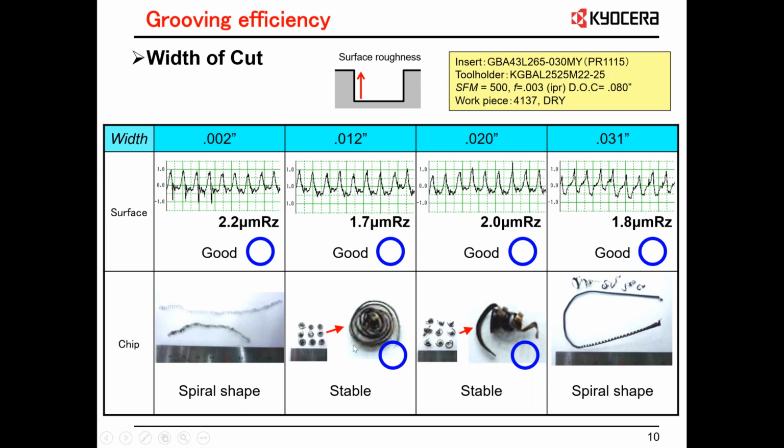Here we're completely engaged to the radius width, and it's running down the side of the chip breaker, where it actually has chip control from that MY because of the way it's positioned on the radius of the tool. Now, the reason these are still breaking, we've gone a little bit beyond the radius width, so we're more engaged into the MY breaker. It's doing a sidewall, so that's why we're still stable, but we're getting a little bit more of a funky chip here, but we still get nice breakage here.